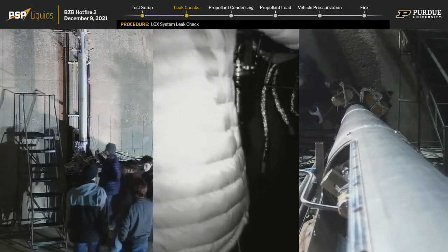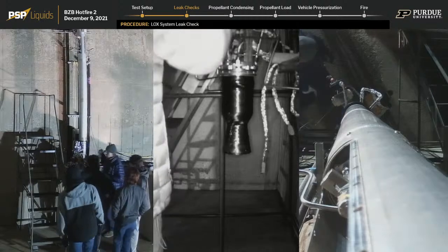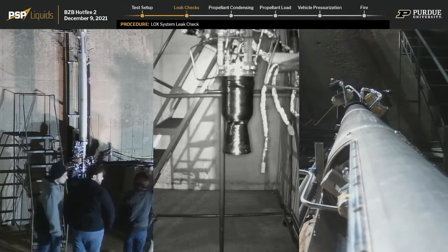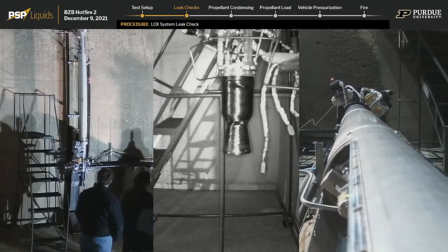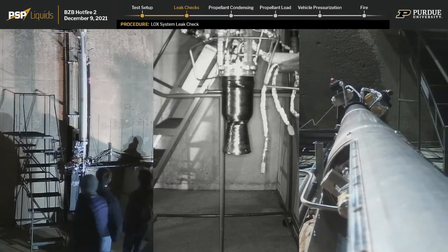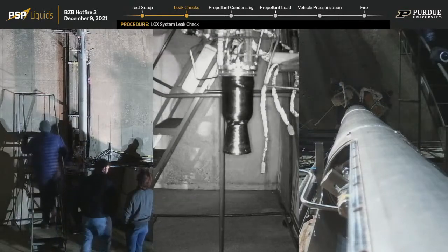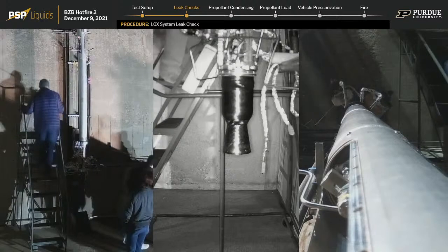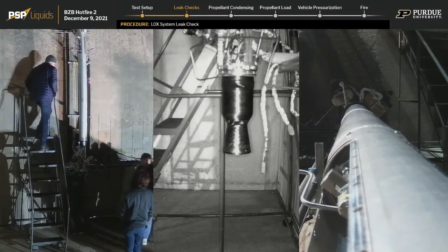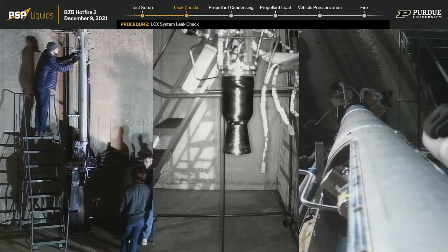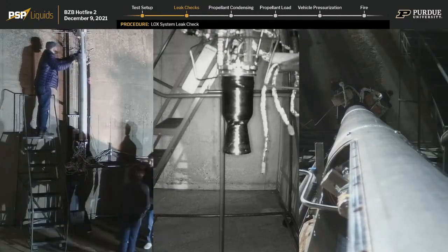Can you repeat that? Over. There's no leaking out of the aux vent line. We also don't hear any audible leaks on the rocket. Over. Copy. We're going to go ahead and get a leak rate. Over. So we're asking for an update: what happened last hot fire? During that hot fire, we have an automatic abort condition that is triggered based off of a sensor reading, and the sensor did fall off nominal, and we've investigated that since. And yeah, that's pretty much it.